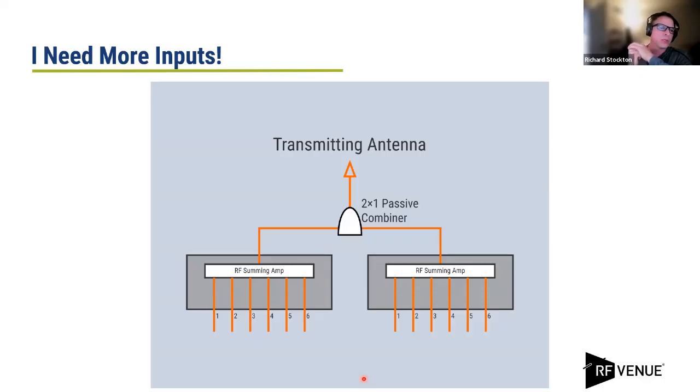And just remember, if you're going in at 50 milliwatts on a 6 input combiner, the output is described as a composite out because it sums them all together. So it's 300 milliwatts coming out of that active port. And that's what active combining does, and that's why when you try to combine two together, you have to be careful with that. And again, the connection from your transmitter to the combiner to your antenna, there's no over-the-air information, so it is very much a different power situation.